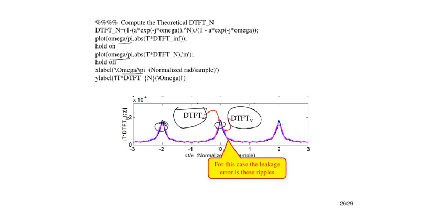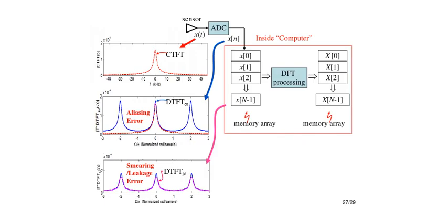Now although we can improve it, even if we append more and more zeros, it will not improve this smearing, right? Because when you append more and more zeros, your DFT will just draw more samples, so it will not reduce this leakage error, right? So zero padding doesn't change any leakage error, that you have to keep in mind. How can you improve it? If you take more and more samples, your leakage will go down, obviously.